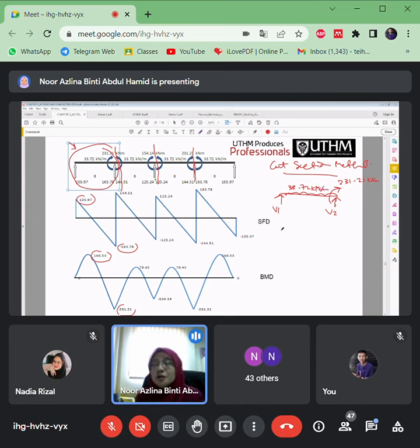Okay, same basic calculation as a simply supported beam here. Find out the moment, let's say at this point. This is clockwise, so 231.21, and then take this load turning about this point here. This is anti-clockwise, so negative 33.72, in kilonewtons, multiplied with the length, and from the length you also need to make it half of it, right?